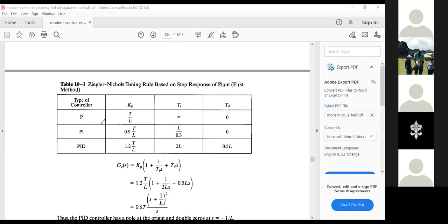The thing about it now is that you have to determine what kind of system you have. So, the common sense discussion that we had before: if it's prone to noise and you want to control the noise, then you need a derivative controller. Notice that you only have three choices: proportional alone, proportional and integral, or proportional, integral, and derivative.